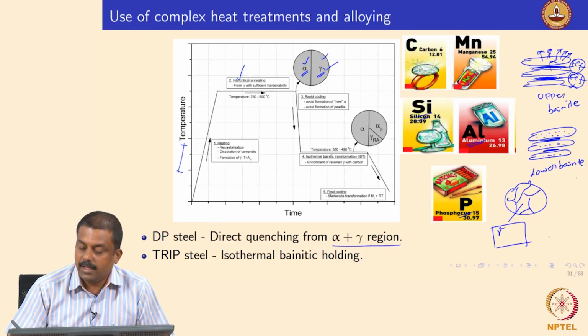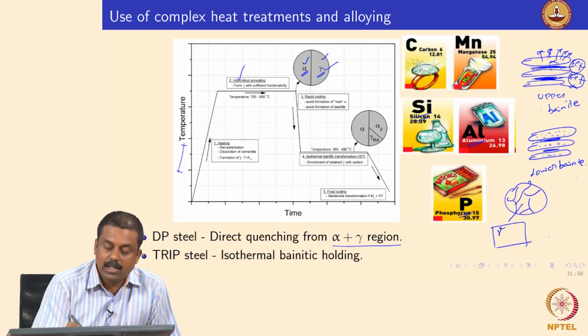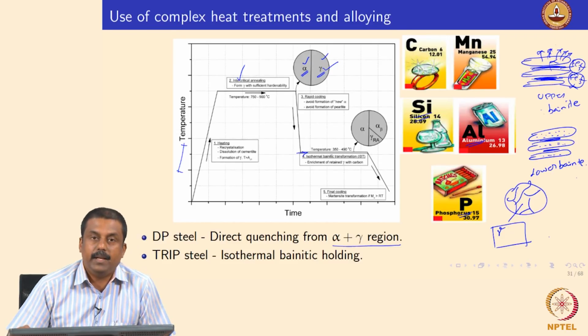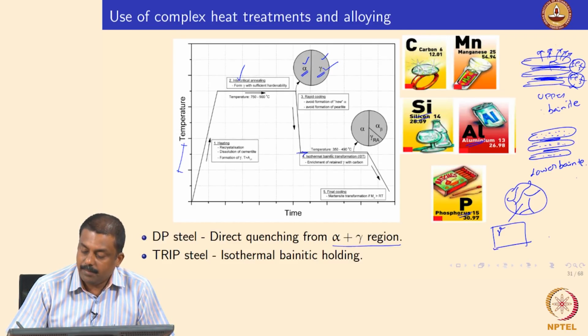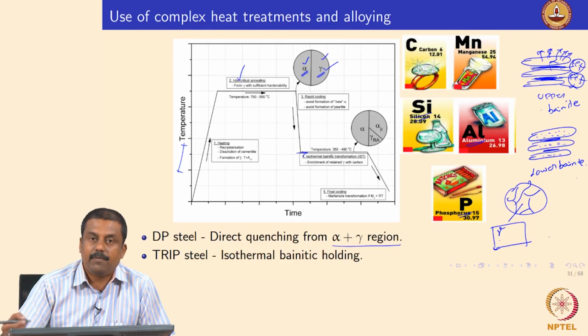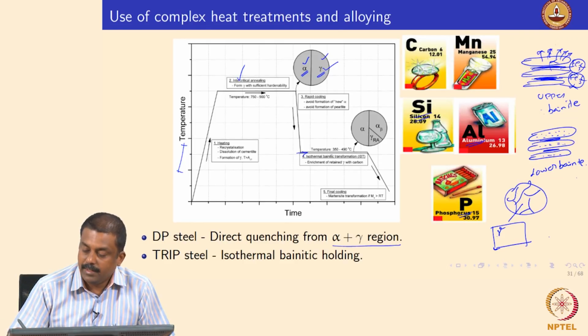and this austenite grain is now held at the temperature where you form bainite. Okay. Now at this temperature what will happen? You tend to form a bainite microstructure. The austenite would transform to bainite during this holding. You first nucleate a ferrite lath, but this ferrite lath cannot hold carbon, right.